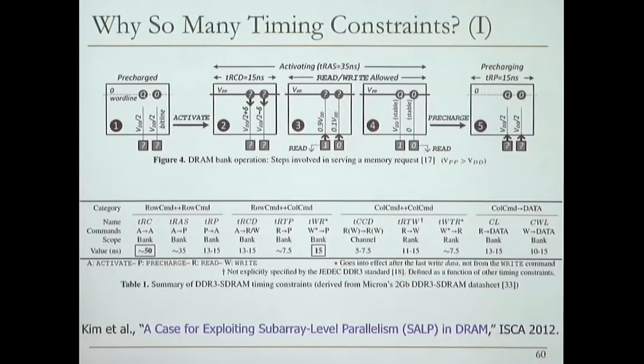Even though you can read the sense amplifier, you still need to restore the data back into the cells, and that takes some time. Until you actually have restored the data that you've destroyed by reading, that's the nature of DRAM, you cannot do some other access. That's why you have a time constraint between activate and a precharge.